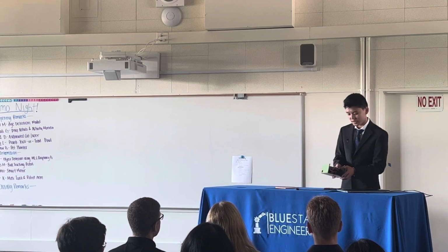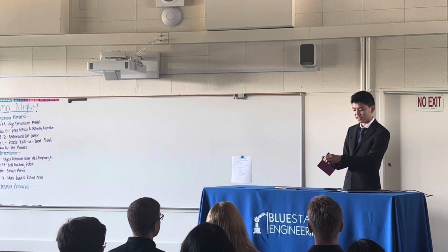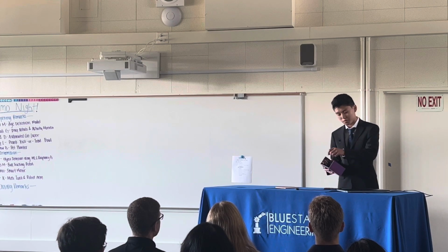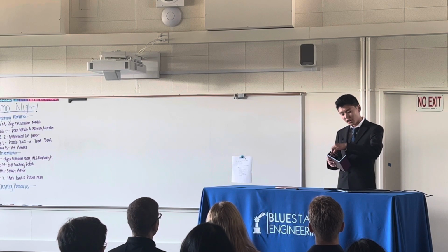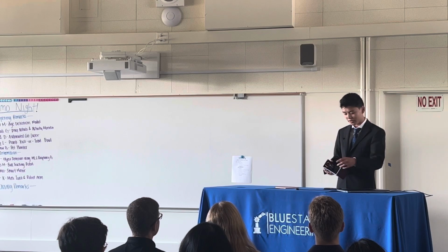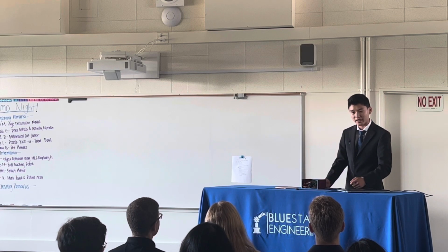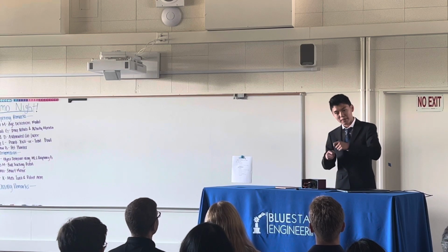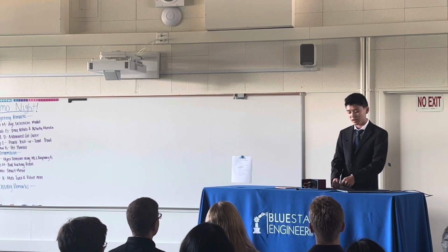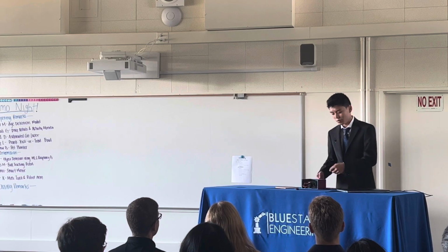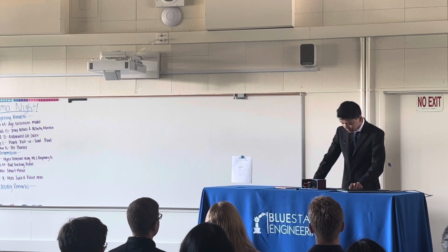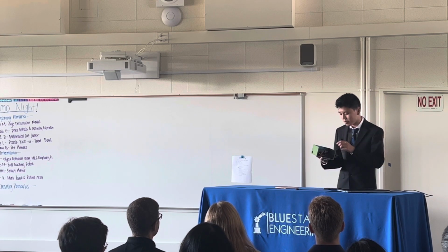Another big problem was these servo motors right here, very fragile. They will very easily break if you pull on the wires a little too hard. One of the wires broke very recently, and I had to fix it by literally opening up the motor, resoldering the wire back into the board inside the motor, closing it up again, and reassembling the servo motor. Another big problem is the button right here.